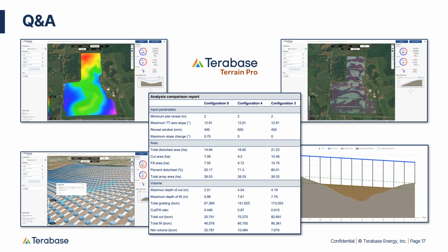Okay, so this is a good question. In one of the examples, and we could even look at the examples on this screen here, if we look at configuration 3, we've got a cut of 82,000 bank cubic meters and a fill of 90,000 bank cubic meters. So that's going to result in the need to do more fill than we have cut. So the net volume there is 7,670 bank cubic meters. Is there a way that I can balance that?